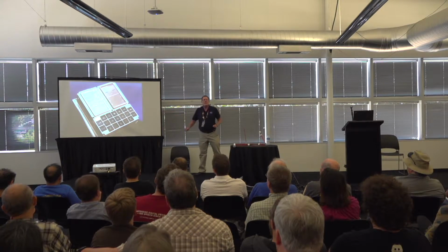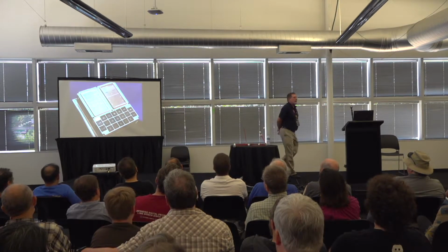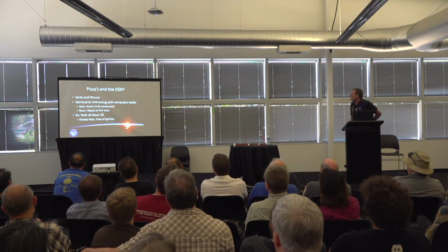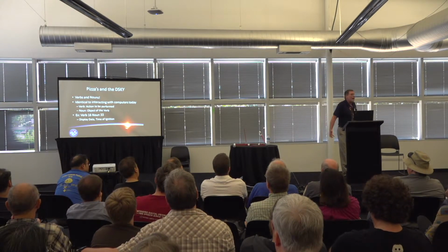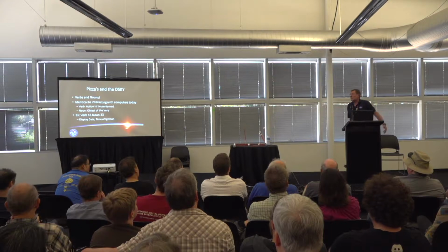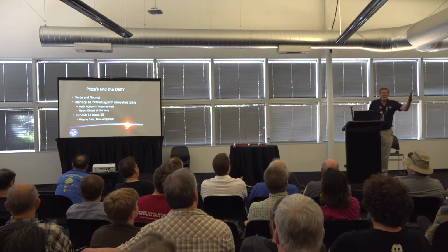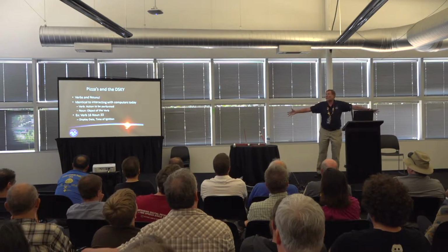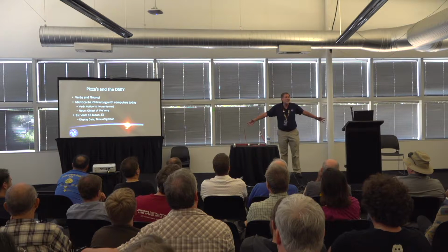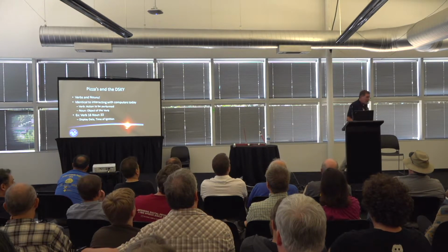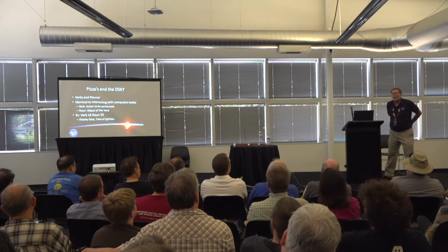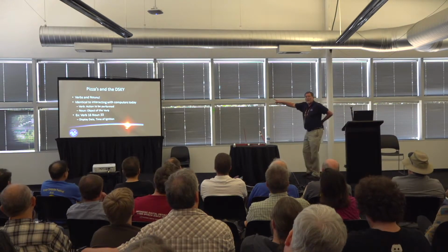Take a look at those keys over on the left. The two primary keys on the Apollo computer are verb and noun. That's how you interact. A verb is an action. A noun is what we want to act on. So eat what? Pizza. Everything has a numeric code. Okay, verb 6, or 16, we display data. Well, what data? How about the time your engine's going to fire? Useful information in a spacecraft. Very, very cool. And if you think, oh, very clever, very nice, now I know how to fly to the moon, and it is. It's all you need to know to run the DSKY.